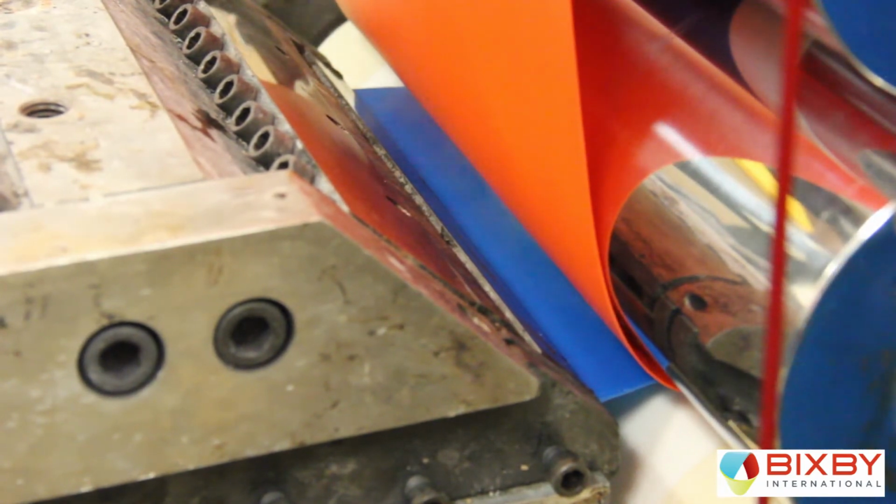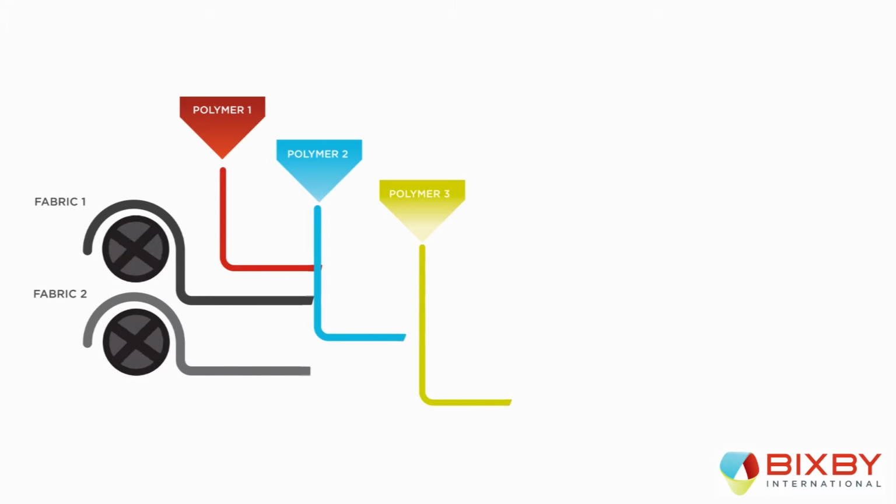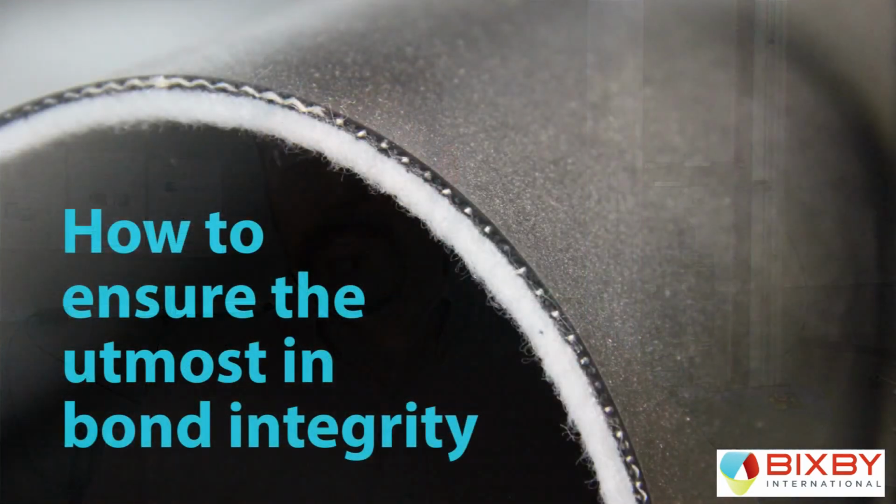If any of the functional layers are found to be incompatible, so the foam isn't bonding well to the extruded substrate, Bixby can modify the tie layer chemistry by taking two different compounds or additives to make that tie layer compatible to both the superstrate and substrate. Additionally, you could surface treat any of the superstrates or substrates being used. So you could take your foam and corona treat that foam to give yourself more surface energy to improve the bond. Similarly, you can use primers. So you could coat a primer onto one surface, making it more compatible with a tie layer, or directly extrudable with a functional layer that Bixby would extrude, whether that be a urethane or a polyamide. This is crucial because anyone who's worked trying to bond laminate layers together understands that getting good wet out is critical to ensuring a good long-term durable bond.